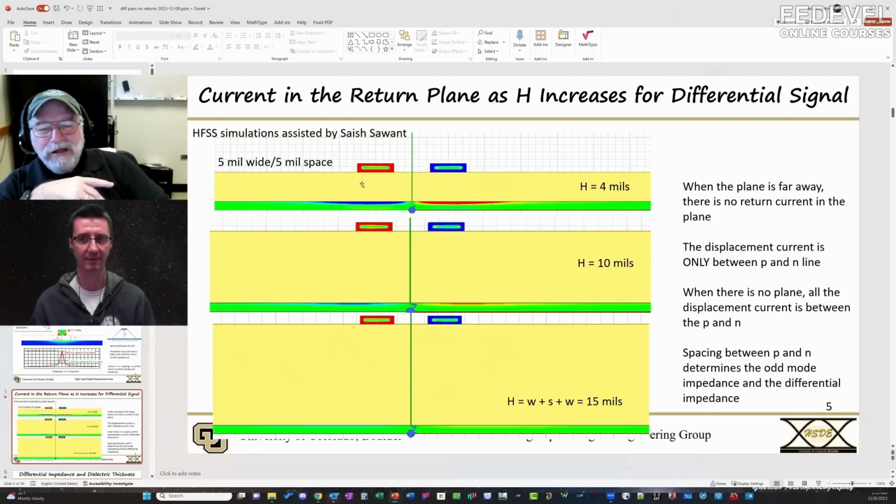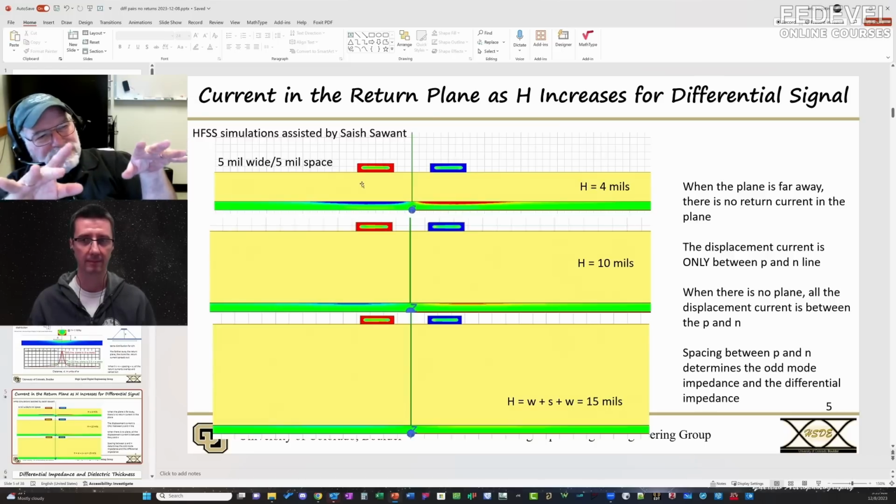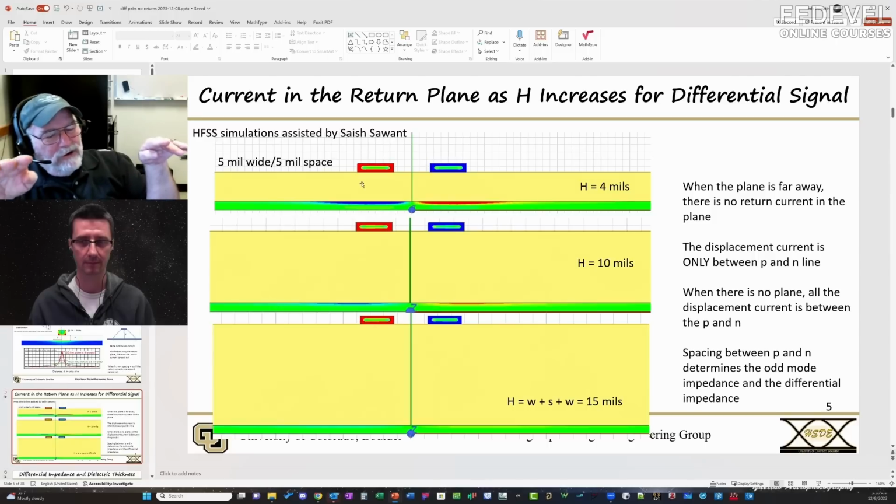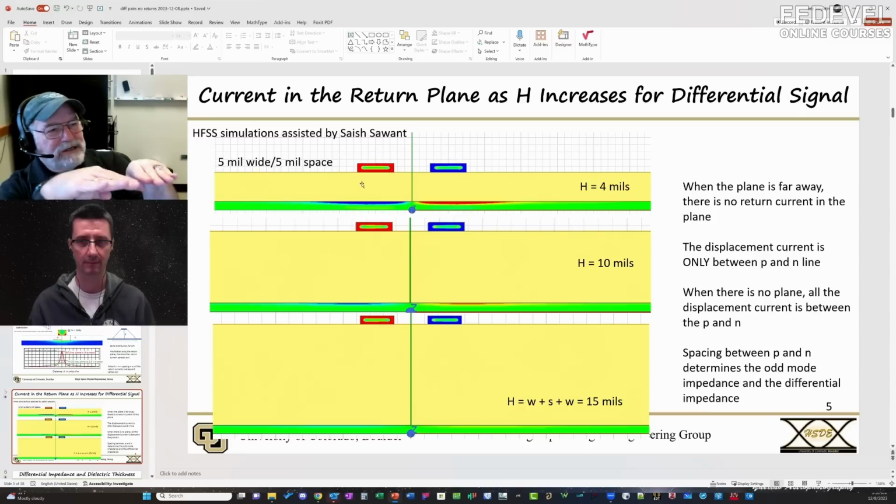Right, you're absolutely right. You can engineer the same impedance line, whether they're close together or far apart, by adjusting the relative line widths. I'm teaching a signal integrity projects class this semester, and I had a student team build a couple of transmission lines where they're far apart and uncoupled, and then brought together really close.